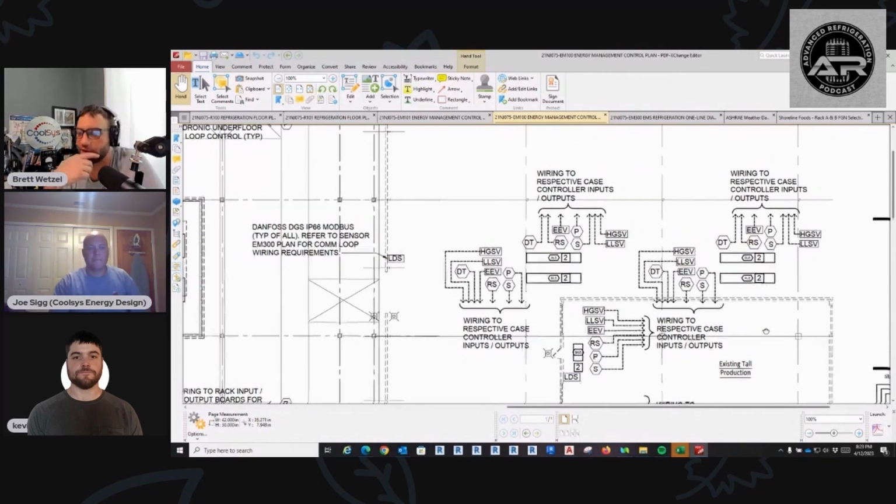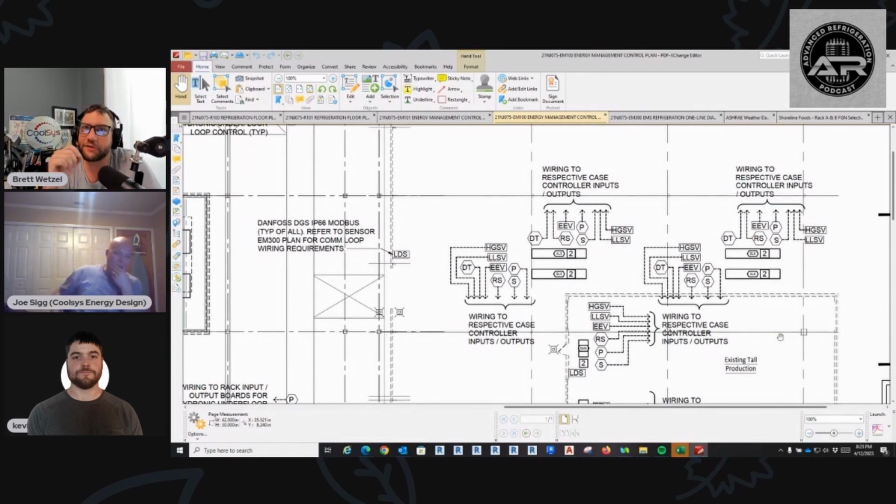Okay, so I have a question about that now, because we just went to the NASRC out in Cali, and they were talking about EPRs in the system, and they were like, well, you're always going to put a check valve in parallel. But then I thought about it. If you're using an EPR for temperature control, it's going to make that pressure higher than the outlet, so it's going to start bypassing on the check. So what he said in the training doesn't make any sense to me. If you're just using it as a suction stop, it would probably be fine. But you can't use it.